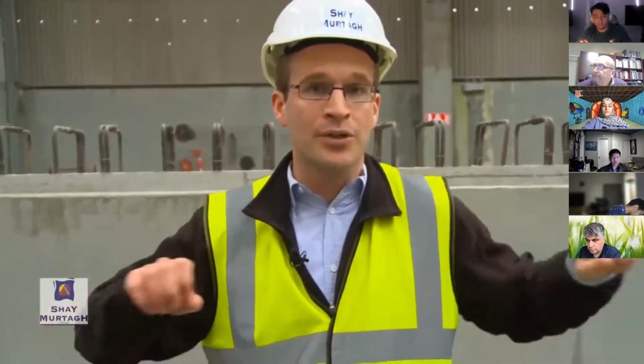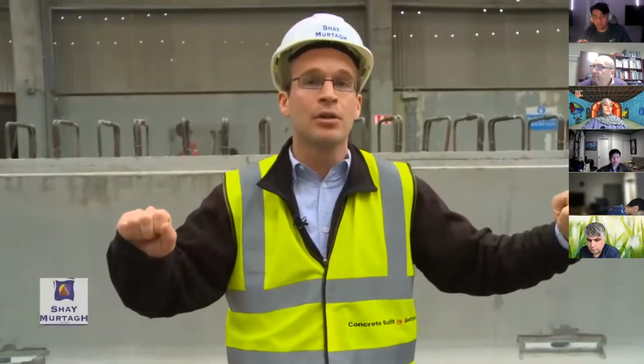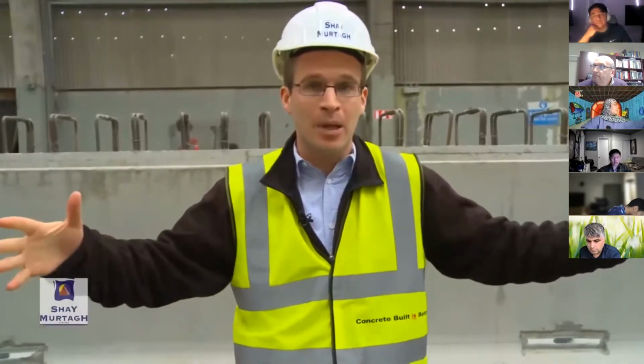The force is applied using pre-stressing strands. Pre-stressing strands are stretched. Concrete is cast around the strands in pre-tension concrete, and the strands are slowly released, thereby applying that compressive force to the beam while simultaneously applying a moment to the beam that also acts to relieve the applied moment.